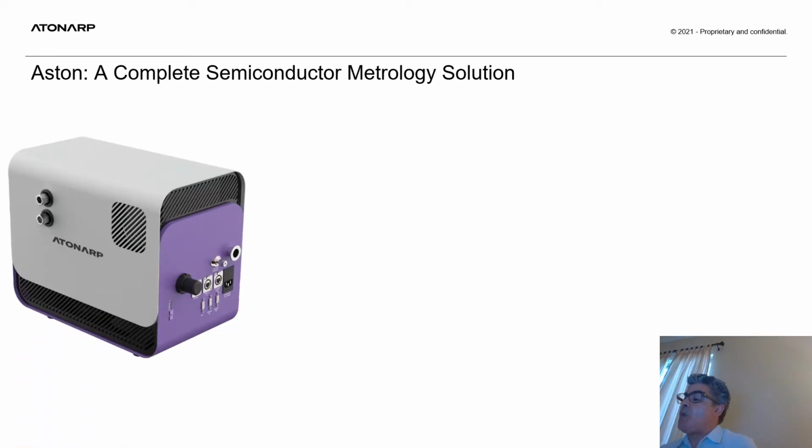ASTON can be connected to the process chamber via two sample inlets. The top one is for both plasma ionization and electron impact ionization modes, while the bottom one is for electron impact ionization mode only. Shown on the front panel are, in addition to a universal AC power inlet, connections including an NW16 flange for connecting the roughing pump, Ethernet communication ports, RS-232 DB9 ports for peripherals such as an optional sample inlet module, micro USB ports for software upgrades and debug, and finally status LEDs.